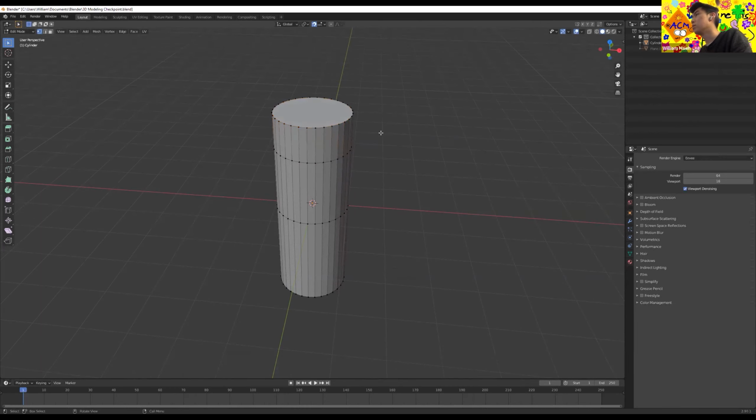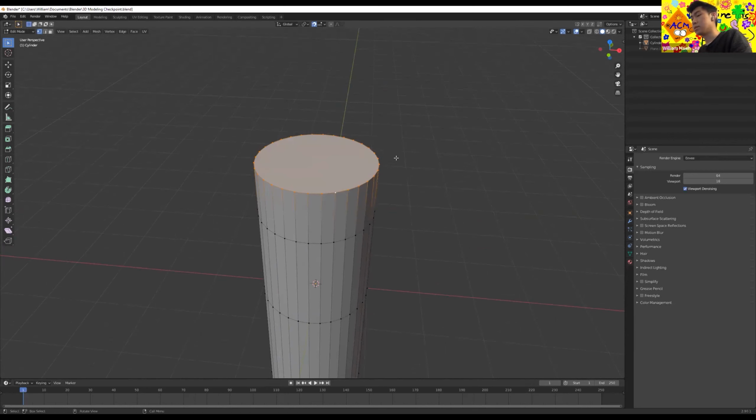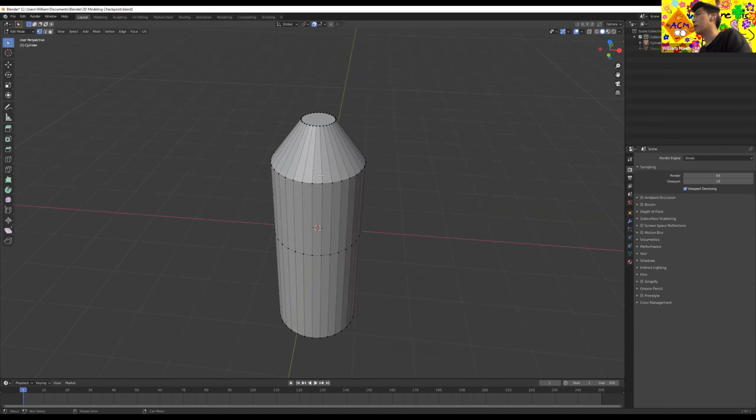All right, I'll go over this again. Select the vertices by Alt clicking or Option clicking, and then press S and move your mouse to scale it down. Okay, once you've done that, we're going to move on to, okay, I'll repeat it one more time. We're going to Alt click, and that selects the loop or the circle, and then press S, which stands for scale. And once we do that, we can scale it down, and then left click to confirm.